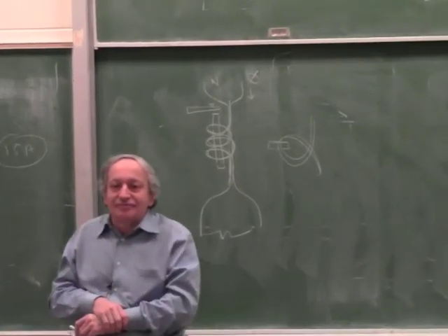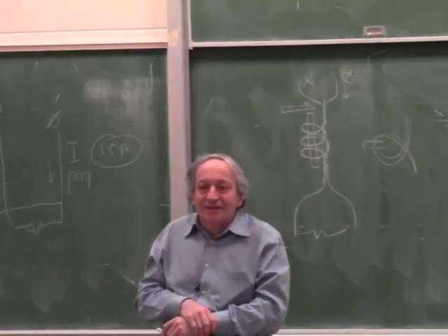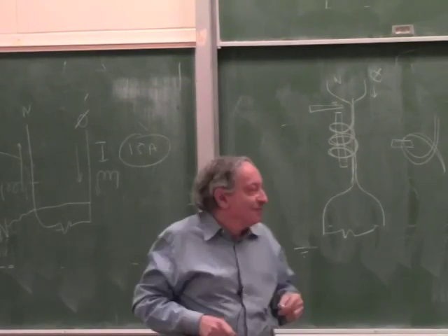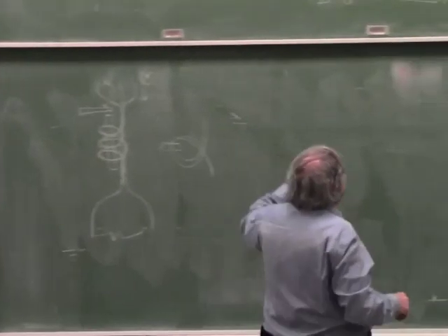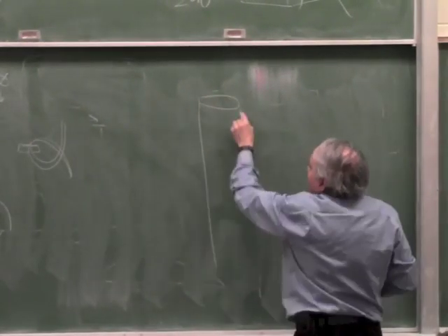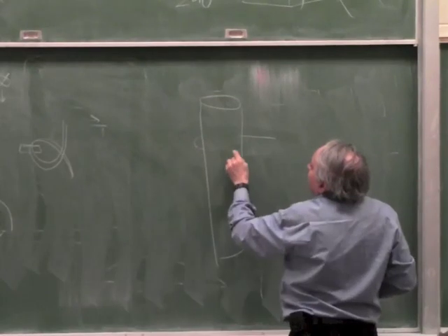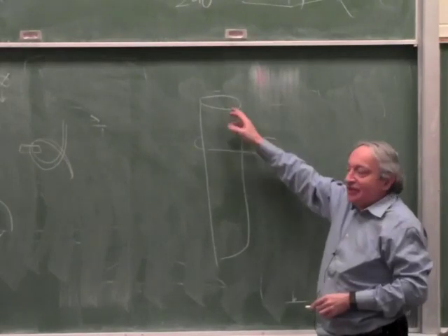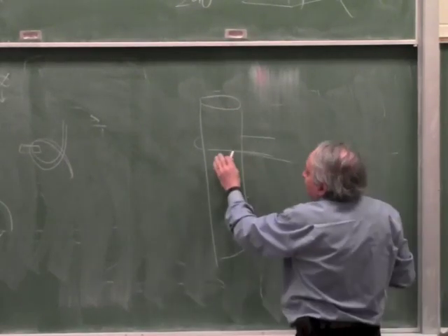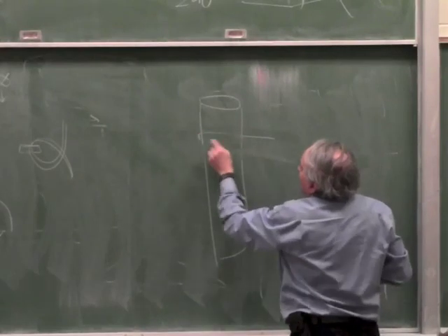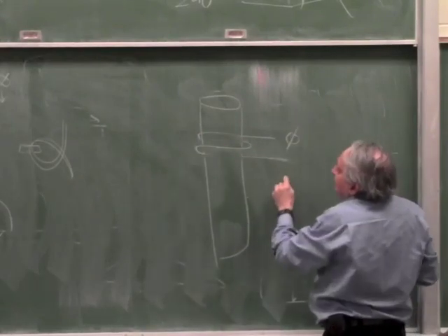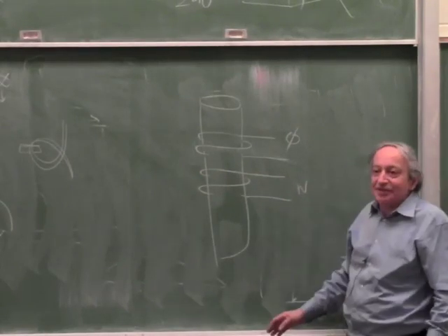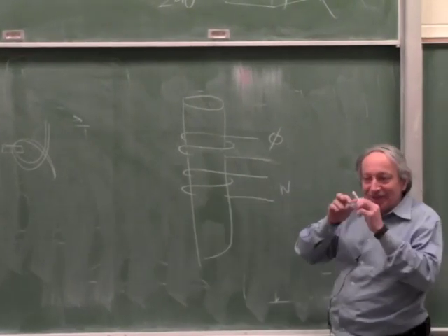Yes? Putting the two wires next to each other, they're still different, because of the distances between them. True, but luckily when you wind it, it doesn't matter, like I explained with the LVDT, because in electromagnets it doesn't really matter where you put the turn, it wouldn't change the magnetic field. You can move it back and forth. So even if you had on the same rod two separate windings, it'll still work. If you have one winding for the phase, and even a completely separate winding for the neutral, as long as it's on one flux path, it will still cancel out. So it's not important if the wires are really close or not.